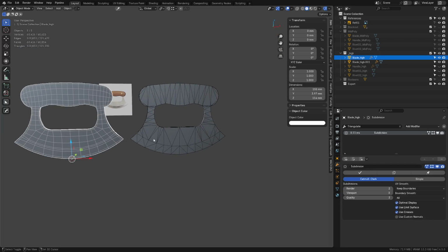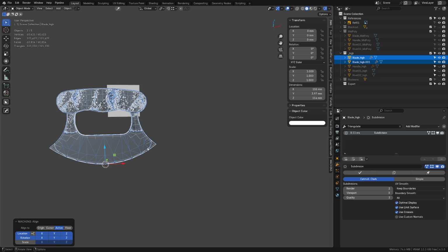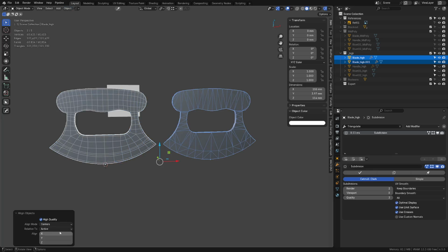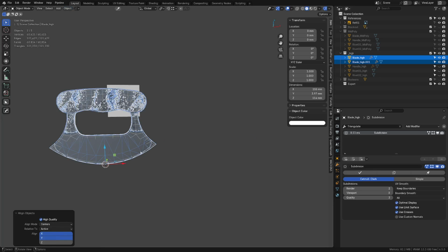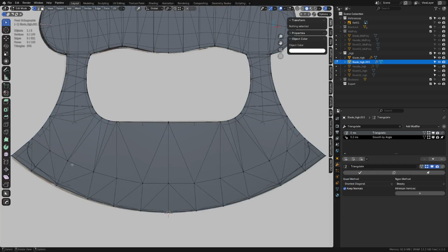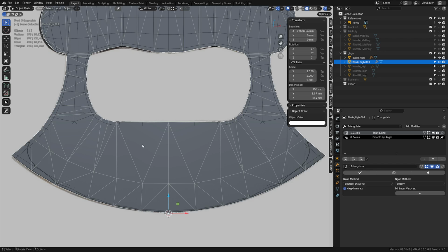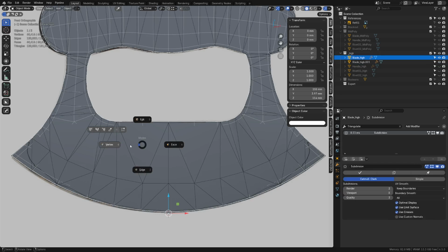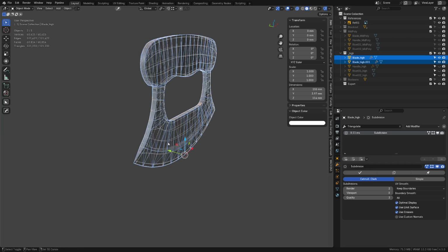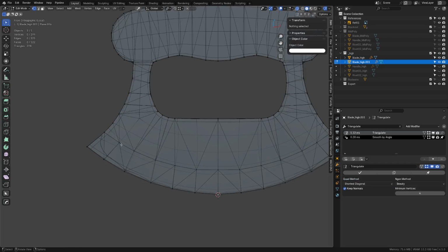So the low poly in this would align, right? So Alt A, oh, grab this one, then this one, Alt A with machine tools, or actually transform, align objects. As long as they have the same origin point, you can hold Shift and select X and Y and align them that way as well. Now, your low poly, you'll UV map it and unwrap it and all that, right? Get ready to bake. But the problem we're going to find is that sometimes it's hard to see them both.